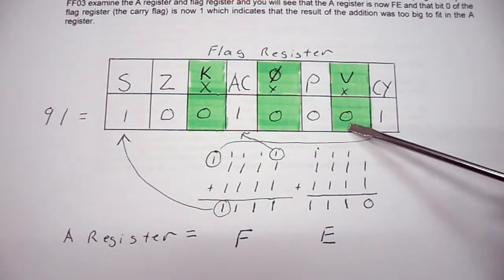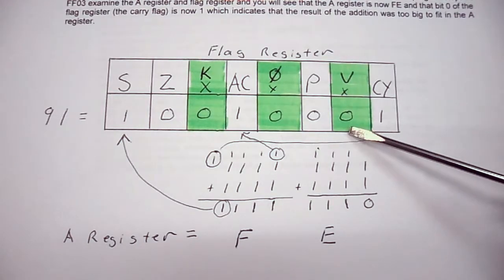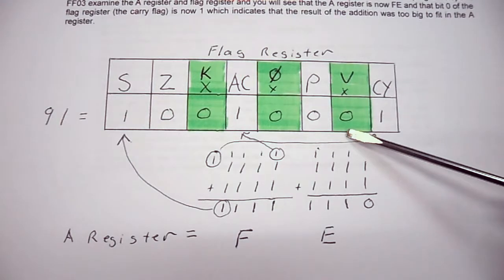Now today we learned about undocumented flags and that there are undocumented commands within the 8085. But keep in mind, if you start using these, they're not guaranteed to work the same for every single 8085 manufactured, because some of them were manufactured by different companies. So it's not good programming practice to use these, but you're more than welcome to try them out. You'll not damage your Primer Trainer doing so.